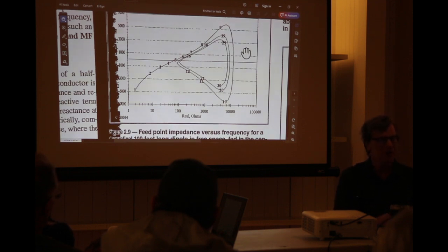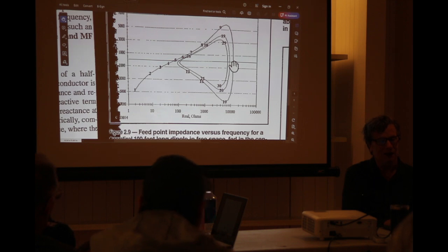Now, what's the earliest half-wave antenna going back historically, 100 years? A Zepp, right? Zepp antenna. And what was a Zepp antenna fed with? Ladder line. How long of a ladder line? A quarter wave, a Q section, which means that anything that you had a very high impedance here, but that quarter wave section brought it over to the back to the low impedance side again.